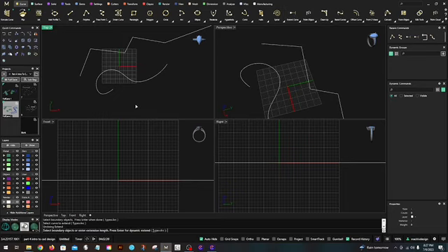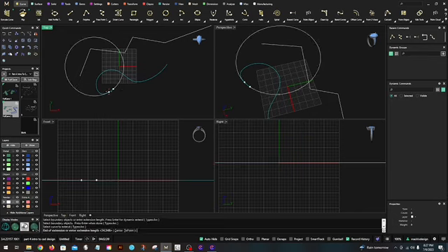Extend curve by arc. So select boundary or objects. There we go. Press enter when done. And select curve to extend. And I'm going to extend it this far. End of extension or enter extension length.